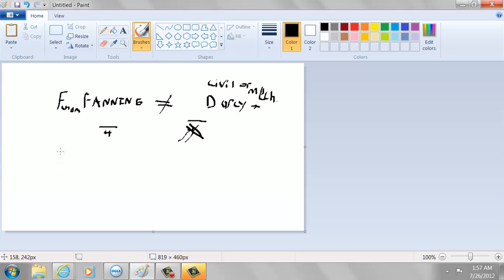And Poiseuille's equation can be rewritten as the friction factor equaling 16 over Reynolds number. And this is the Fanning.